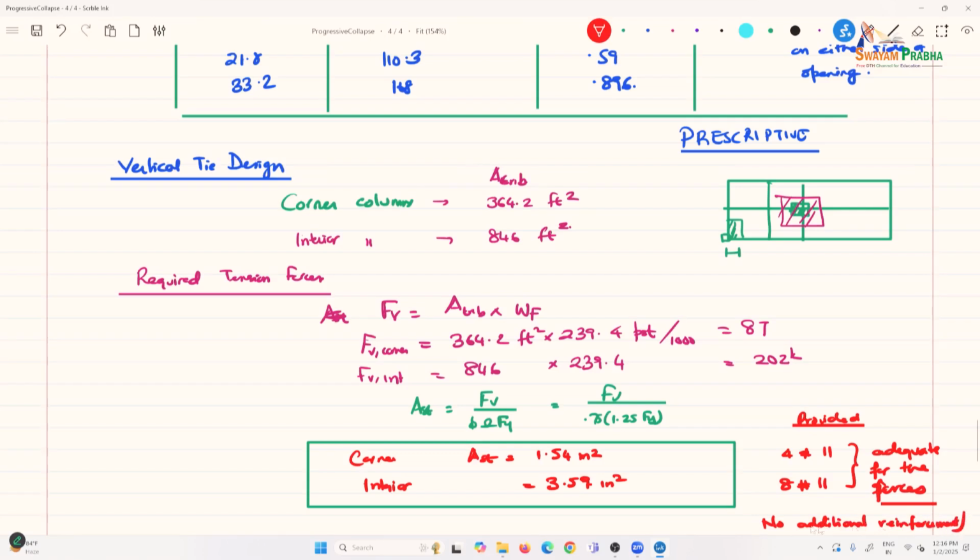These are in tension. Typically, your reinforcement is acting in compression. So when this tie action comes into play, these are pulled apart. This corner gets tension, so your column reinforcement is in tension now. So ensure continuity, full continuity. That's the main thing you have to do here.